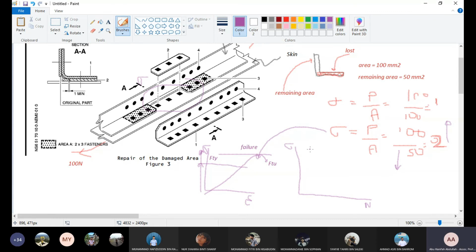Secondly, there is the stress and cycle curve. We go back to mechanics of materials, you learn about this. If you failed mechanics of materials, you may have problems understanding. So, on the stress and cycle curve, as you increase the stress, the cycle will be less. It was here before at lower stress, now the cycles, this is life.